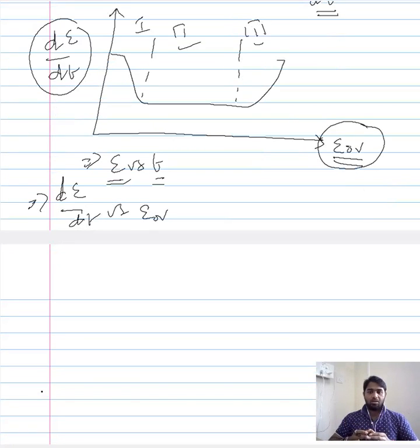The first one considers how much strain occurs over a period of time, and we have plotted that. That is a conventional way of representing creep. It has different stages, and now instead of considering the time on the x-axis, we have considered the overall creep. What we have essentially done is studied the small amount of creep strain that is exhibited by a material during a small period of dt, and then we have plotted that in relation to the overall strain, and we were able to get a plot that is something like this, and that also reflected the different stages of creep.